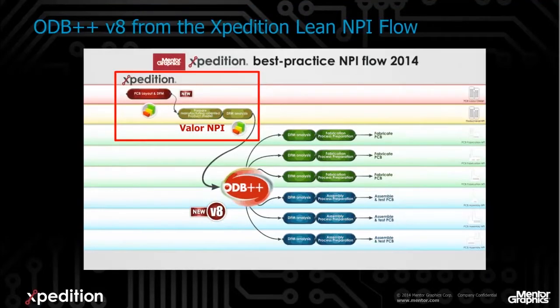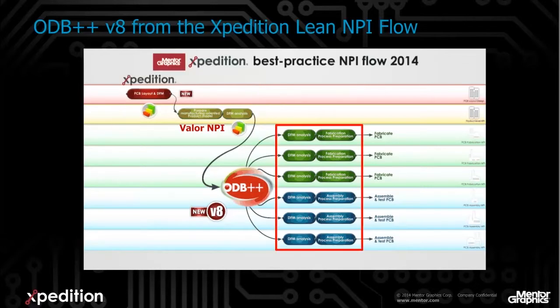We have now covered the product NPI flow, starting with DFM verification embedded in Xpedition, through to comprehensive product modeling and verification, bringing us to the point where we are ready for handoff to the process NPI phase, where the execution-ready manufacturing processes will be generated. The manufacturing level product model is ready for handoff, comprising a complete definition of the PCB to be fabricated, assembled and tested.